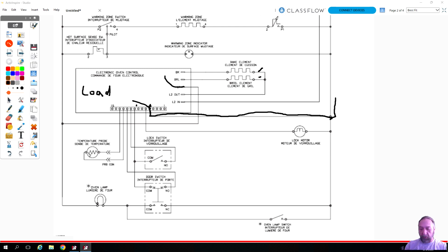First of all, like I said, let's start off with something simple. If you got this stove and the stove's not working, where do you want to check for power? The same 2 points that I put my wires for power. I have it on line 1, which is here, and my neutral there. So I have 120 volts live there.